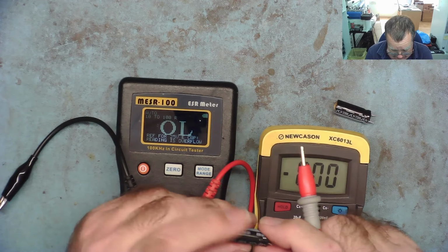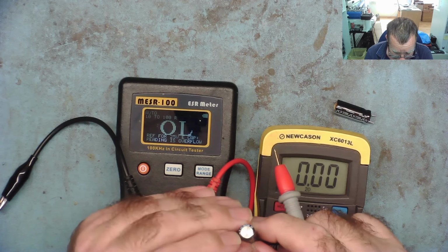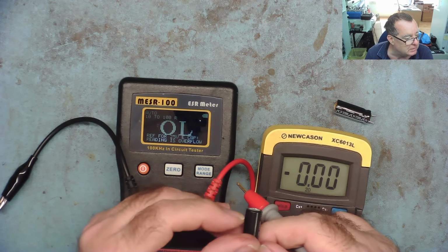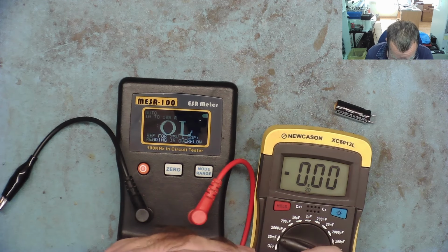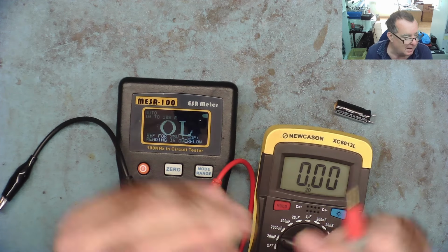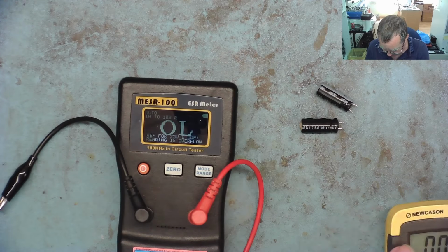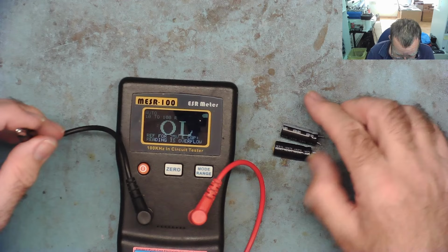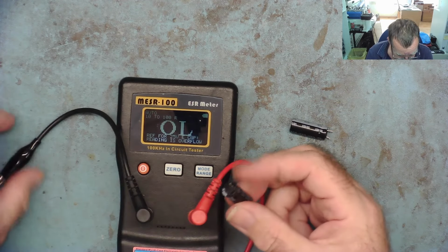Let's look at this one. So this is another one that isn't leaking, but it is bulged. Can you see the top of that is like curved outwards? It's like a dome. It's convex. Yeah. What's this one reading? Again, this reads much higher than it should be. Now, this is another way that sometimes capacitors fail. These will probably read okay on the ESR meter, but they're obviously not. I mean, this one clearly isn't.